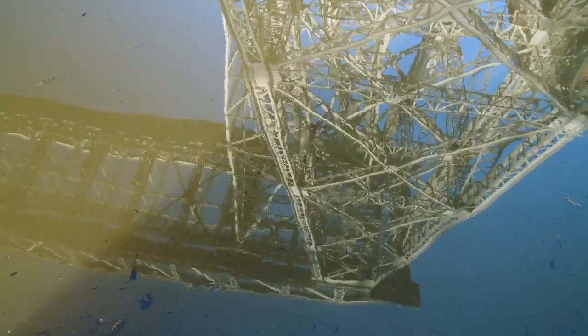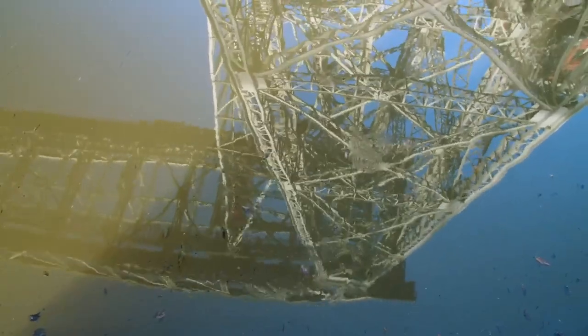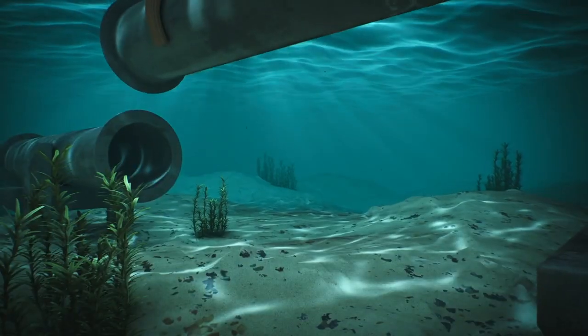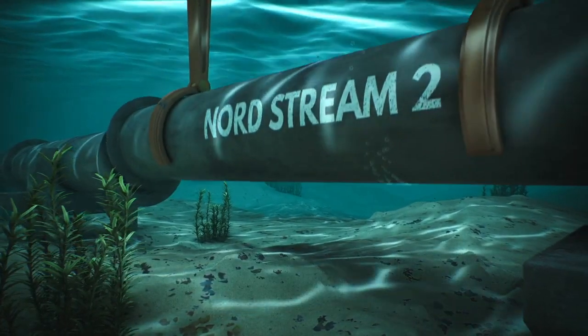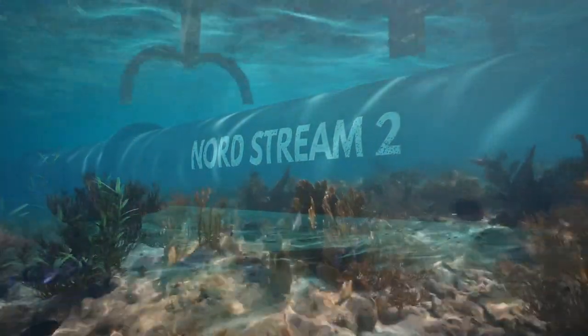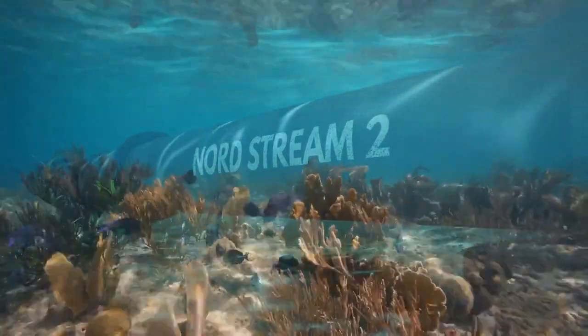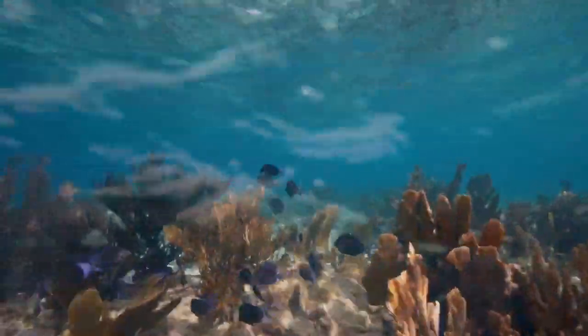Because there's one piece of information you need to know: the design lifetime for one wind turbine is about 20 years. So when we choose the foundations, we need to consider after 20 years, what kind of environment we are facing. For example, the current may bring the sand away. For example, the fish may need to live around those foundations. So when we install the foundation, we also need to consider environmental impact.